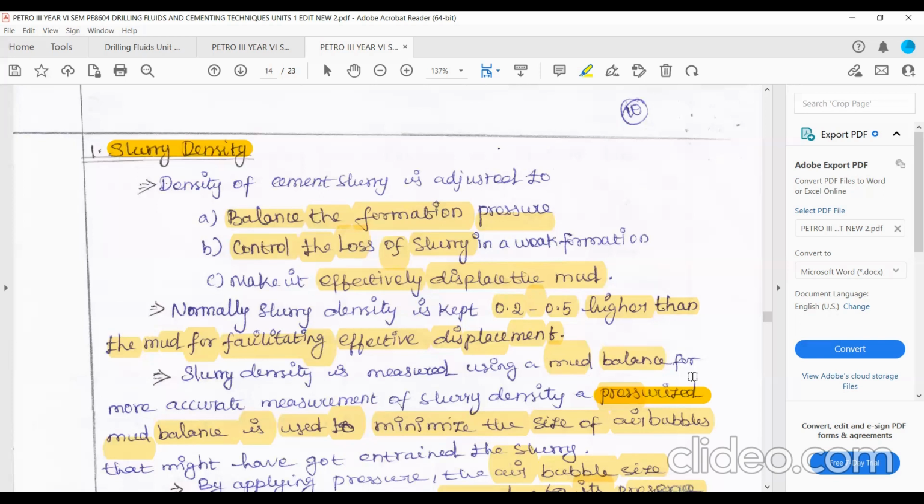the heavier the cement slurry, the more easily it could displace the drilling mud, because these are alternate operations. First, drilling fluid is sent along the drill string, cools the drill bit and collects the cuttings. We send it in successively. The next fluid is sent to push the drilling fluid, and it is called a spacer fluid.